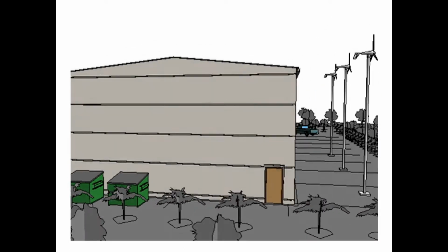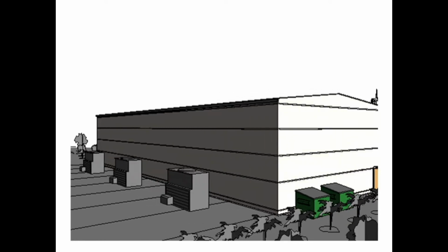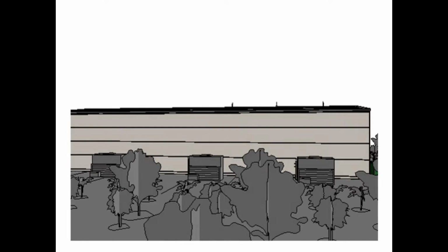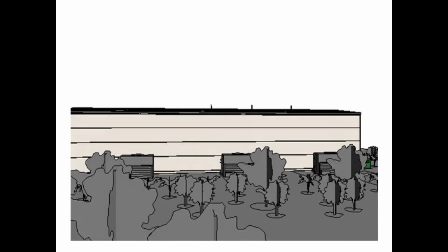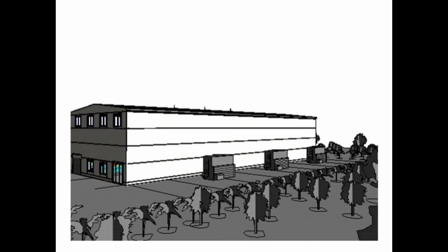The parameters for the building structure have different specifications that are appointed by the client. Group 22 has been instructed to build a portal frame with length 40 metres, width 14 metres, eave heights of 8 metres and a roof pitch of 6 degrees, with a rafter load of 10 kilonewtons per metre.